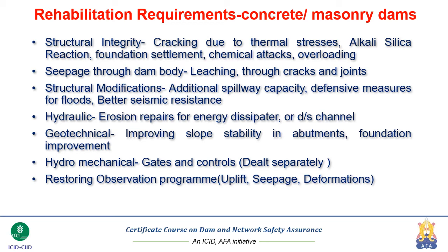Structural modifications, where we may need to provide additional spillway capacity. Now this becomes a very major construction exercise at times. Defensive measures for floods, like providing telemetry in the catchment area, getting better hydrological data and getting better warning times. Similarly, better seismic resistance by adding crucial additions to the body of the dam and creating a body which is more amenable to resistance against seismic forces of a higher magnitude than it was designed for.